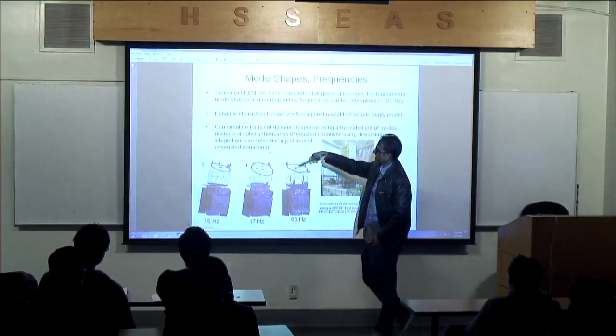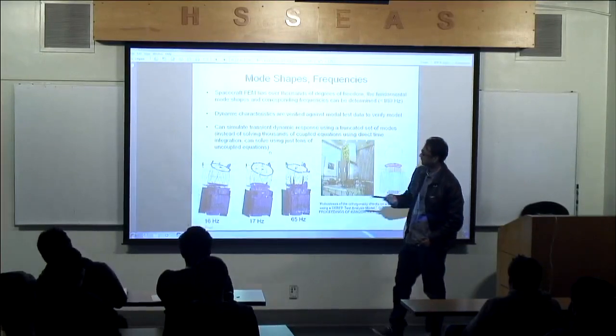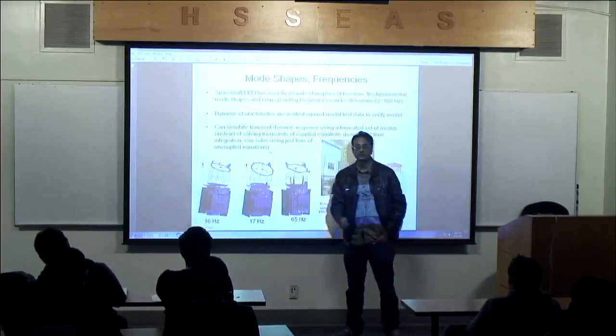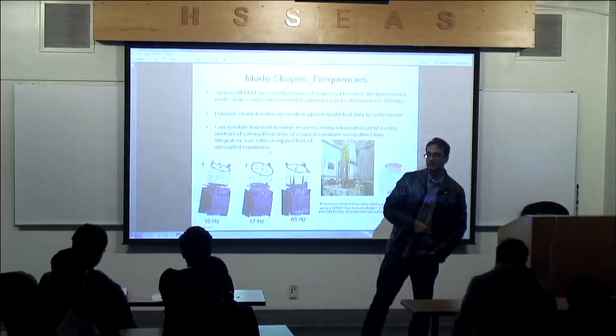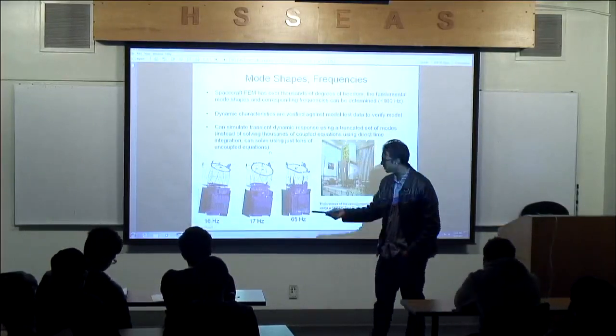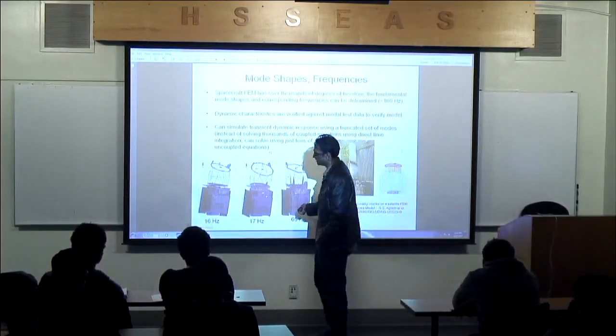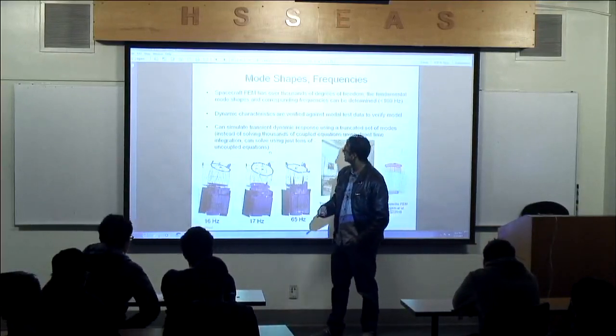So you can simulate the dynamic response, transient response, like what we did on Tuesday, but that would mean I will have to invert million degrees of freedom by million degrees of freedom and solve for every time step as a function of time. Or what I can do is get the mode shapes, and here there was maybe 10 of them. I forget, the paper described them. Maybe there's like 20 of them, say.